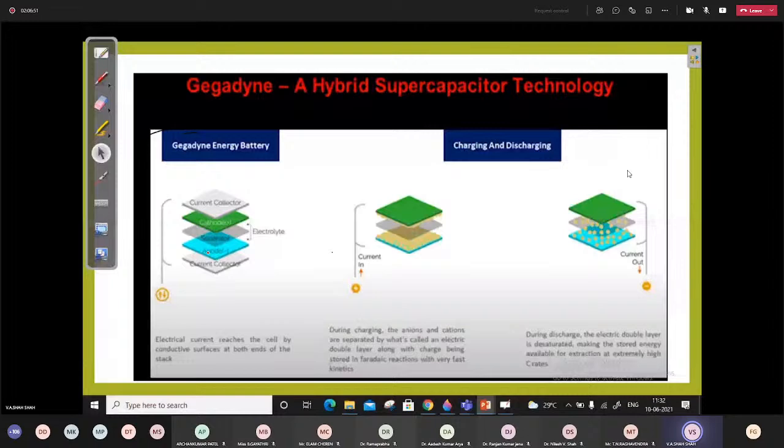And this is again the most important part. This DC link capacitor has to be designed appropriately so that the ripple can be minimized when the power is supplied to the induction motor.